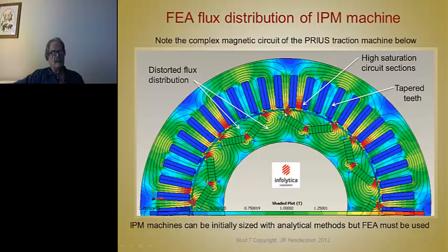That's why that's there. And the thickness of these little webs are also based upon not magnetics, but they're based on the yield strength of the material and the centrifugal forces on the masses that have to be restrained by these little webs. Does the same thing as this. So consequently, particularly in the case where you're forcing flux to go over and have a higher flux density over this magnet than that magnet due to the field. This is reactance. The permanent magnet flux is reacting to the effects of the electromagnet, and that's what causes all these flux densities to distort and to do what they do. So the only way you can analyze that is to use a finite element solver. How else could you predict this?